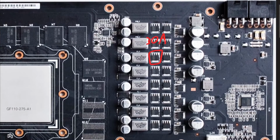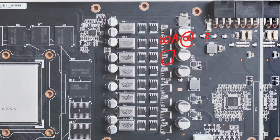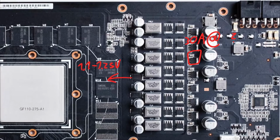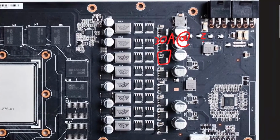It is 30 amps at a certain voltage, which is not always the typical 1.1 to 1.25 volts that most people run their GPUs at. Sometimes it's something like 1.8 volts or 14 volts. And yeah, different voltage means a different amount of current being safe for the MOSFET.